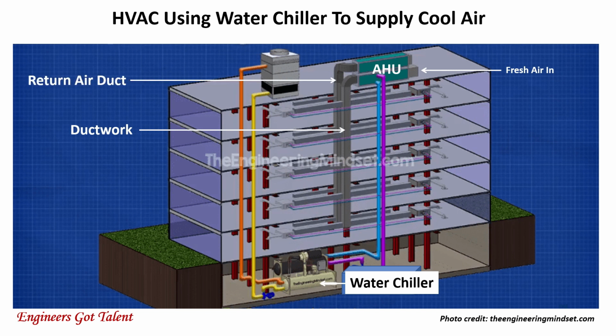The return air duct picks up the heat from the rooms. The air from the rooms is dry and dirty. This air goes to the ventilation, which is part of the AHU. The air is vented or exhausted out of the building. Ventilation is the process of replacing the air from the rooms to replenish oxygen, remove excessive moisture, unpleasant smell, smoke, heat, dust, airborne bacteria, and other unwanted gases from the rooms.